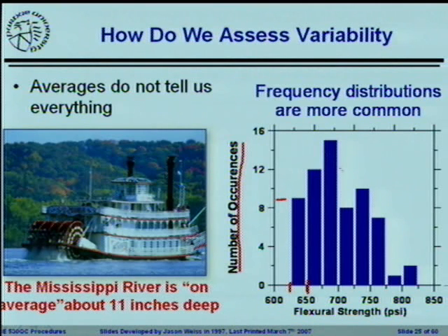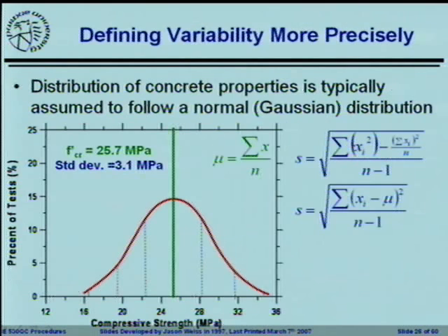And we could get something like this, which gives us a distribution of the strength. So in addition to calculating something like our mean value, which we'll see here, we could also get this distribution, which tells us a little bit about how much variability we should expect from beam to beam. Now this data is actual data from a concrete paving project where they're looking at the beam breaks that are coming back and trying to get an assessment of the quality control and the variability that exists.